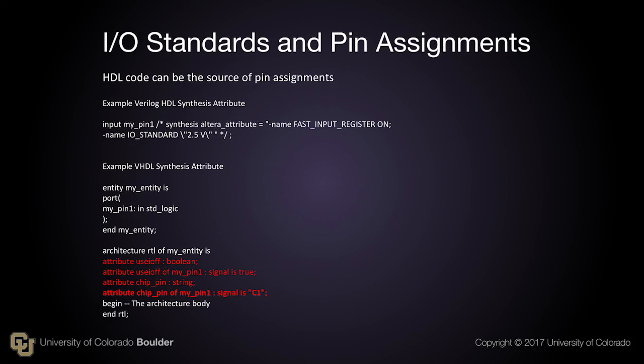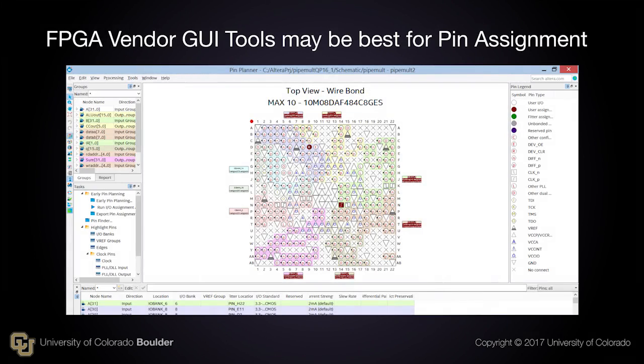It is often helpful to include pin assignments in HDL code, as then the source file for the design and the pin assignments is together in one place. This can be done in both Verilog and VHDL as shown in these examples. Perhaps the most efficient way to make pin assignments is to make use of the FPGA vendor graphical tools. Here is a picture of the Altera pin planner.